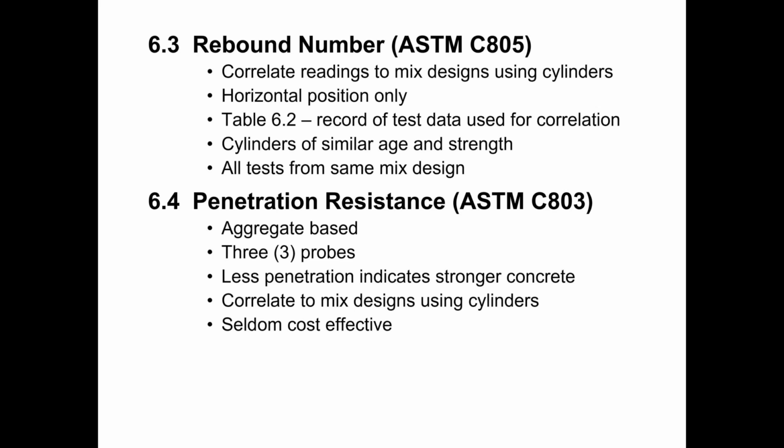We don't want to put it on a soft surface, such as soil, or on an elevated surface, such as a table, because some of the energy from the rebound hammer can be dissipated through the support. So we need to be on a good, solid, rigid surface, such as a concrete slab.